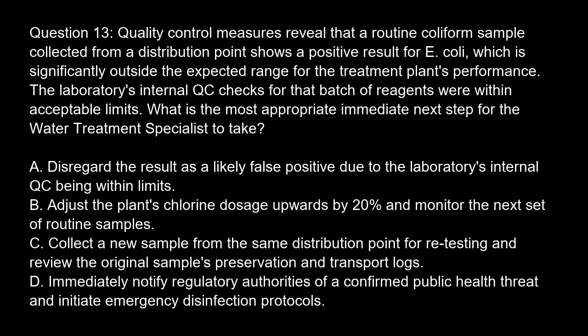Question 13. Quality control measures reveal that a routine coliform sample collected from a distribution point shows a positive result for E. coli, which is significantly outside the expected range for the treatment plant's performance. The laboratory's internal QC checks for that batch of reagents were within acceptable limits. What is the most appropriate immediate next step for the water treatment specialist to take?